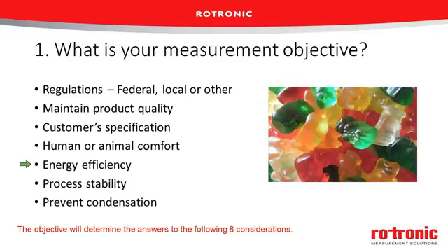There could be process stability considerations. If your relative humidity is changing too rapidly, that could impact the products. So you might need to make sure that you've got a stable relative humidity. Another consideration may be to prevent condensation.